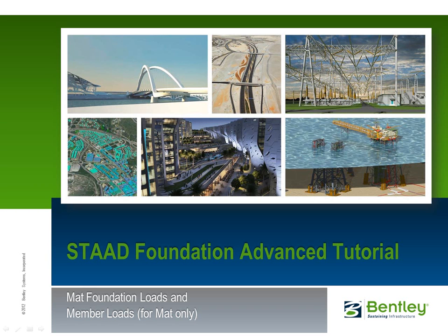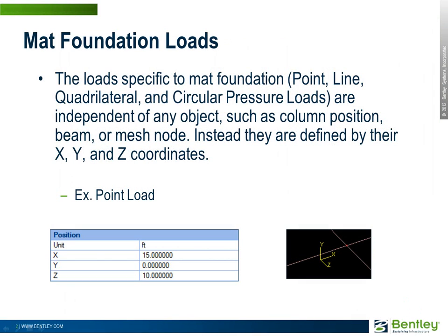This tutorial will cover mat foundation loads and member loads. Firstly, I will specify a few points which apply to all types of mat-specific foundation loads. The loads specific to mat foundation, which are point, line, quadrilateral, and circular pressure loads, are independent of any object, such as column position, beam, or mesh node. Instead, they are defined by their x, y, and z coordinates.